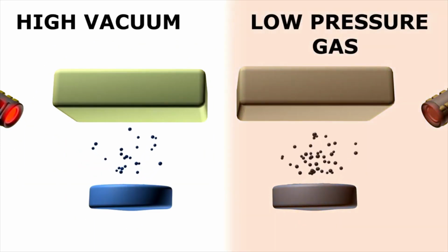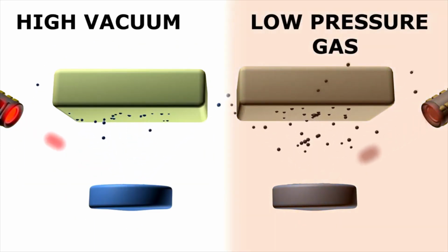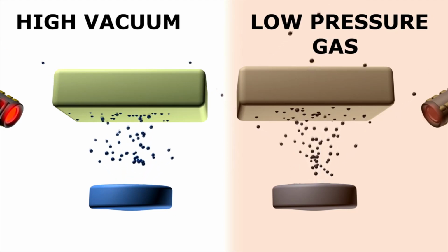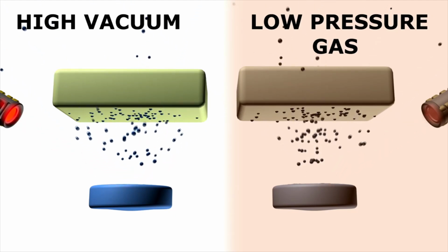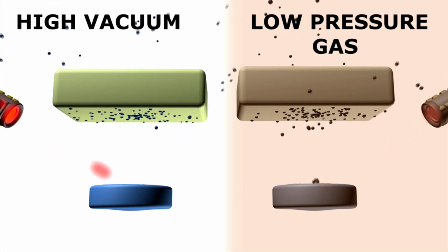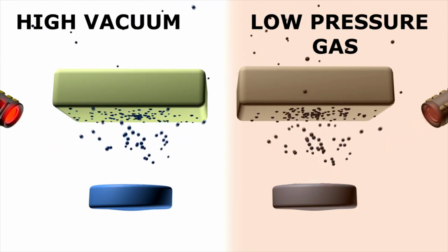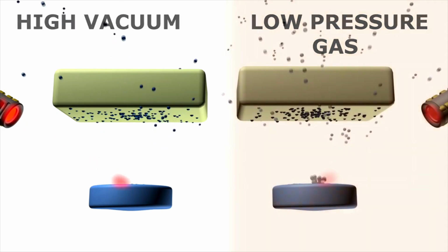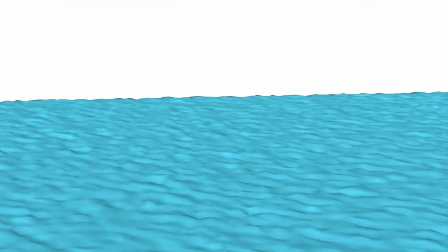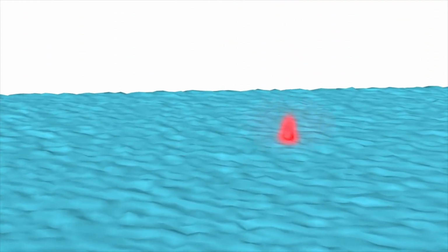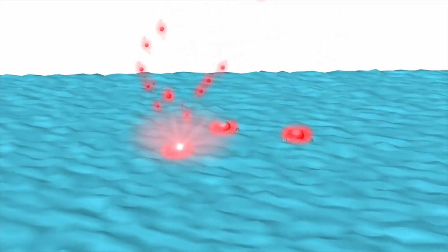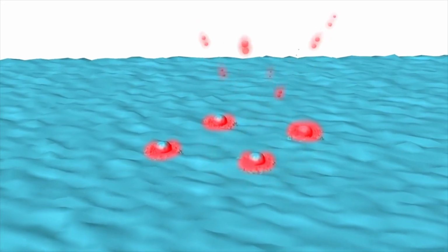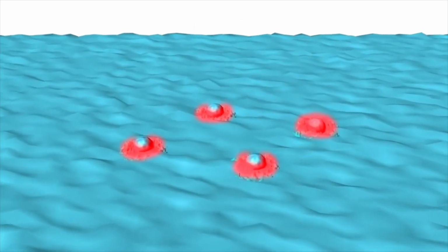It should also be noted that the kinetic energy of the particles arriving on the growth substrate depends on the pressure of the gas in the chamber. Using background gas reduces the kinetic energy of the particles and allows obtaining films with high crystallinity. At lower pressures, the extracted particles are not slowed down and they hit the substrate with a higher energy. This may cause localized damage and sputtering of the previously deposited film.